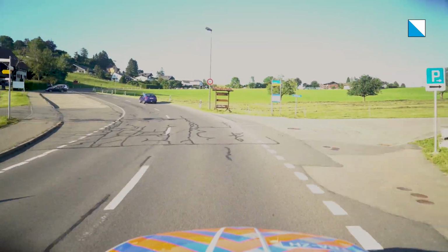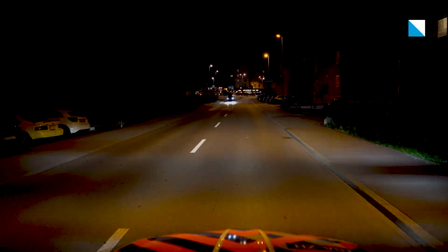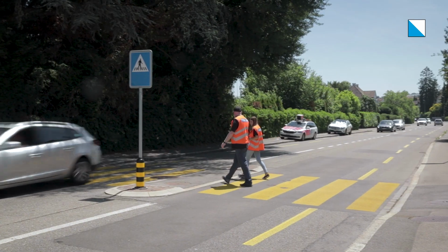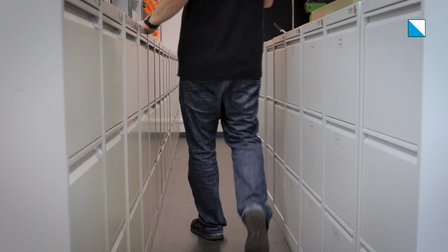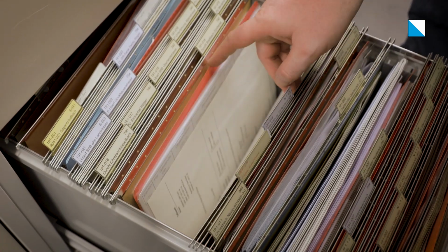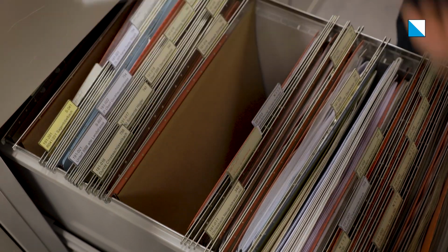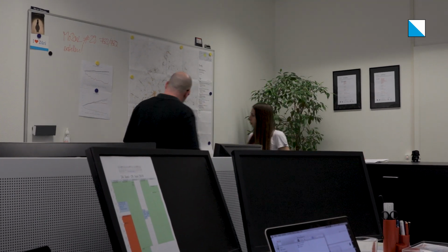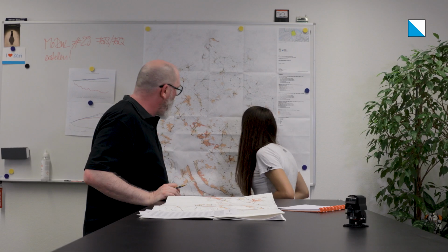There are two types of RSIs. The comprehensive type, in which we examine entire sections of the route, or the topic-specific type, in which we examine all pedestrian crossings along the entire network. After deciding what kind of inspection would be most appropriate, the actual RSI begins. We research and analyze the existing background information, including materials and construction documents and plans from our archive, as well as gathering information from our road databases. This establishes a solid groundwork from which we may start the RSI.